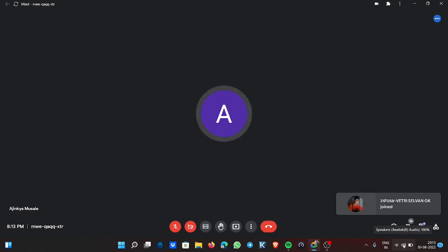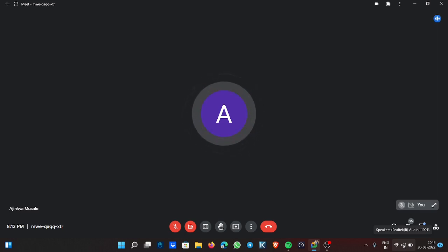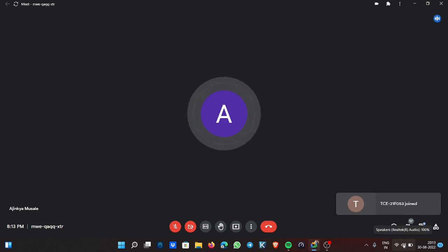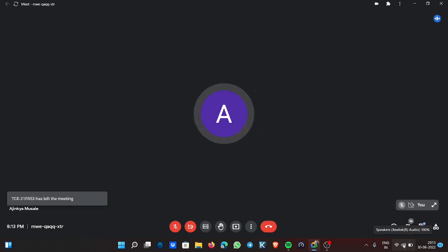So I selected metric. But again, as I saw kg, meter, second, I want it in millimeter, so I shifted it to this one because I want my lengths and everything in millimeters. So I selected the other metric option, right? Now my window is ready to use as a template. Then I double click on Static Structural, or I drag and drop it over here. So I will have one window over here, which is nothing but my problem, whatever I have in my assignment.